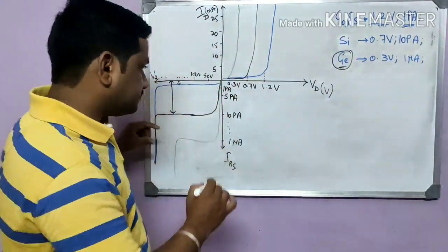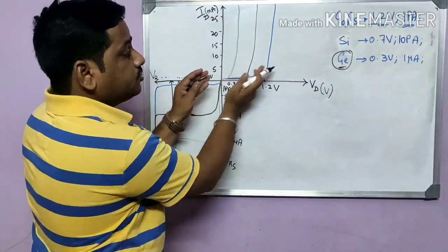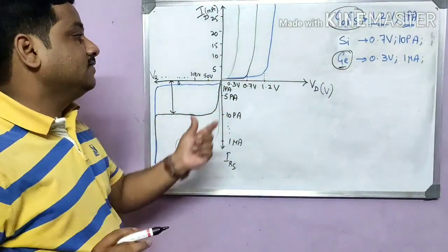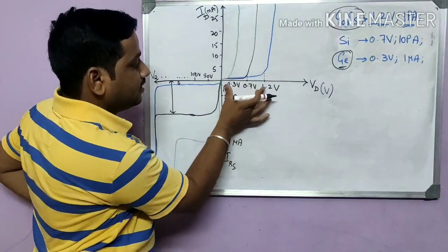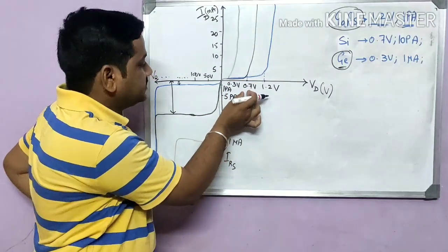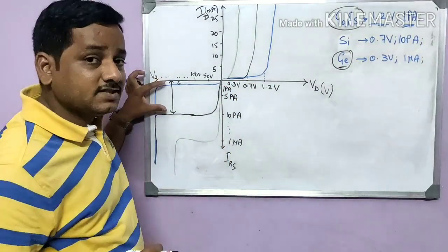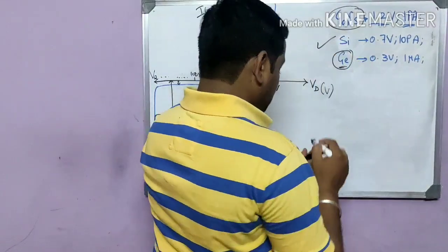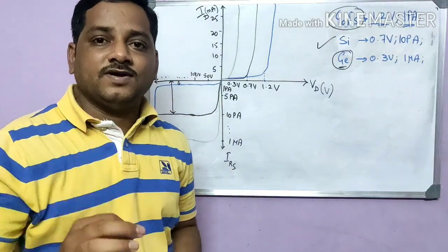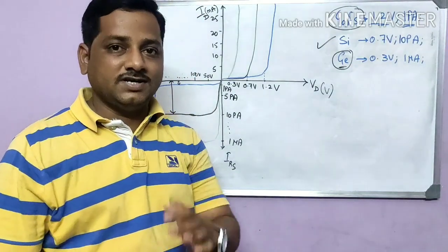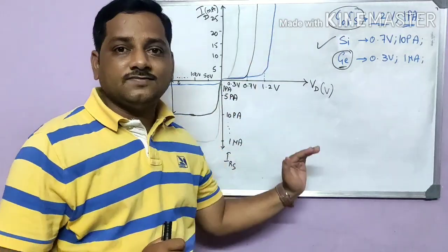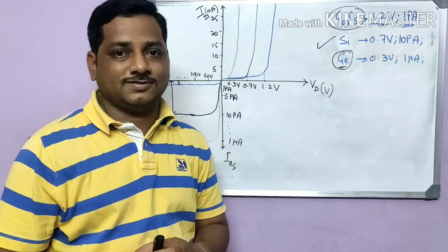Gallium arsenide, the threshold voltage is very high. That's why even this is not used widely. Whereas the silicon diode has a moderate threshold voltage and also a moderate reverse saturation current, but very good breakdown voltage. So that's the reason silicon is the famous semiconducting diode device. Now let's look into the applications of these three different types of semiconducting diodes.